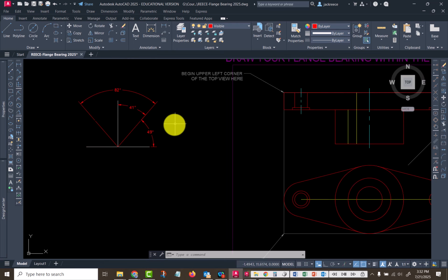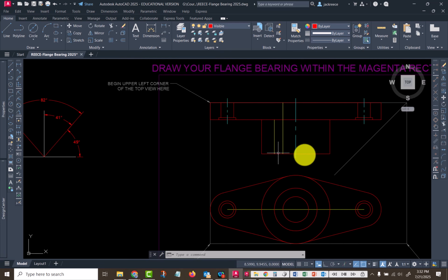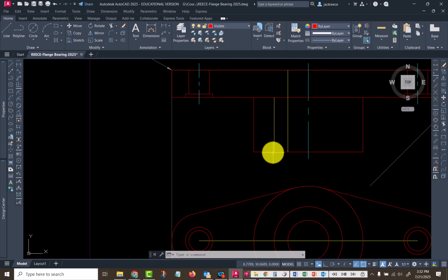And you think about it, how we're gonna draw that. It's actually going to be inverted, but the angle is still going to be measured from a horizontal line. So the one here would be up at a 49 degree angle. And so I'll go line, snap here, come out, and I'm gonna go ahead and tell it 2, and then tab 49 degrees. Okay.